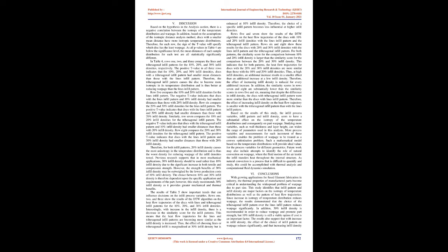Previous research supports that in most mechanical applications, 30% infill density should be used rather than 10% infill density due to the significant increase in both tensile and compression strength. However, the strength benefits of 30% infill density may be outweighed by the lower production costs of 10% infill density. The choice between 10% and 30% infill density is therefore dependent upon the specific application and requirements of the part. However, this study recommends 30% infill density as it provides greater mechanical and thermal benefits.